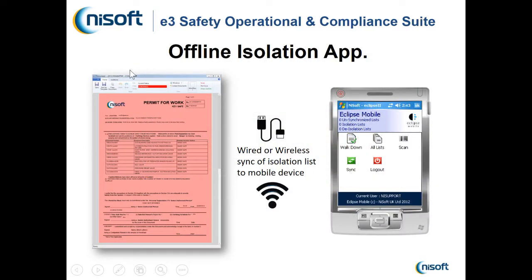The first part of the process is just going through and setting up your permit, specifying the isolations that you want to carry out, and you get to the point where you want to apply those. But instead of printing them out onto a form that you take out to the site, you sync those with your mobile app. This then is acting as an electronic isolation list. You can then take that application out to the site along with your printed isolation tags and apply them to each of the points, using the mobile app to identify where those points are and what the details are.